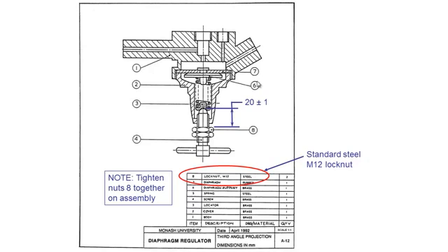One thing to note on this drawing is we have the drawing and material columns, which were separate in one of our previous examples. They are now combined, and the rest of our information here is in fact all from detailed drawings, so you'd refer to the detailed drawing for their full specification. Also worth noting is that they might not have had access to the drawing number, so they haven't put the drawing number there, but they've included the material. Generally, we'll split those into two, so you can have a drawing number column and then the material column.